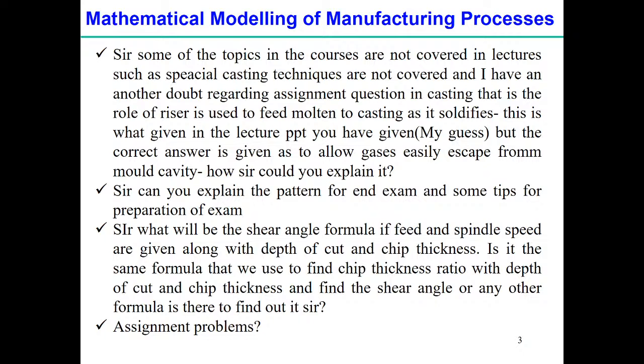The riser's sole purpose is to feed the molten material even at the last stage of solidification, such that whatever shrinkage volume exists within this mold cavity during the casting process will be made up by the riser material. So that is the objective and purpose of using the riser.